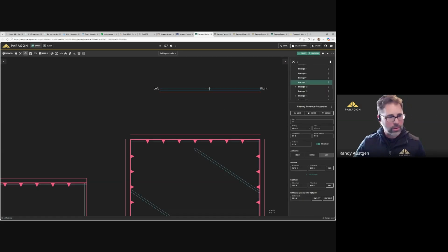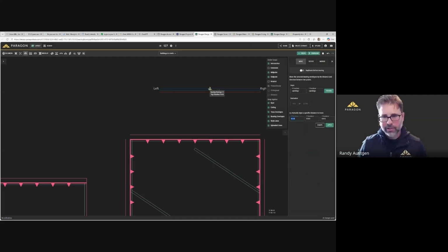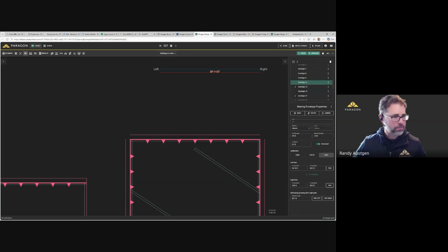The only gotcha there, and we are at time, is if you are performing a math function, for example a calculation, and you're using the minus operator, you have to make sure there is a space between the preceding dimension and the trailing dimension. And I always tab out of the command just to see the math before I hit apply.